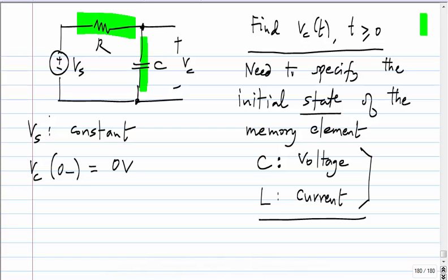Vs by R. Just after t equal to 0, a certain current starts flowing because the resistor has some voltage across it. So it has to have a current, and this current has nowhere to go, it will go into the capacitor. Now, as it goes into the capacitor, what happens? The capacitor will start charging, at what rate? What will be the rate of charging? Current, yeah. So what is it? Vs by R.